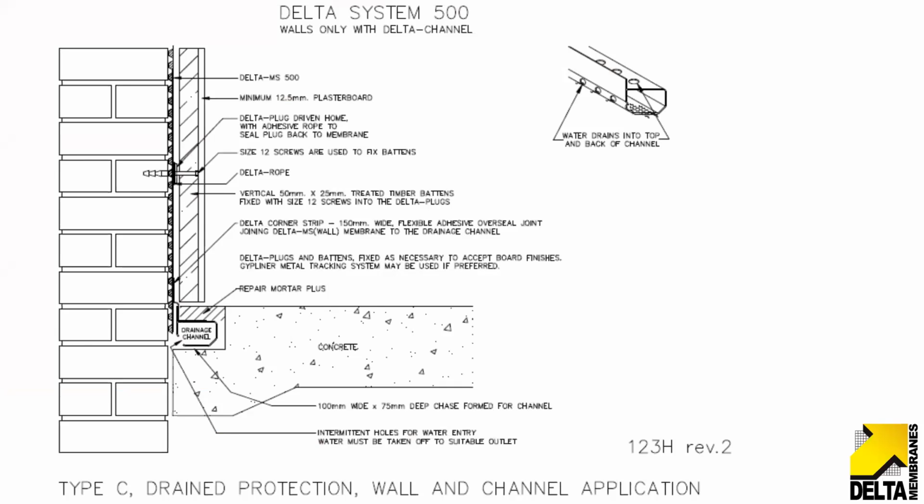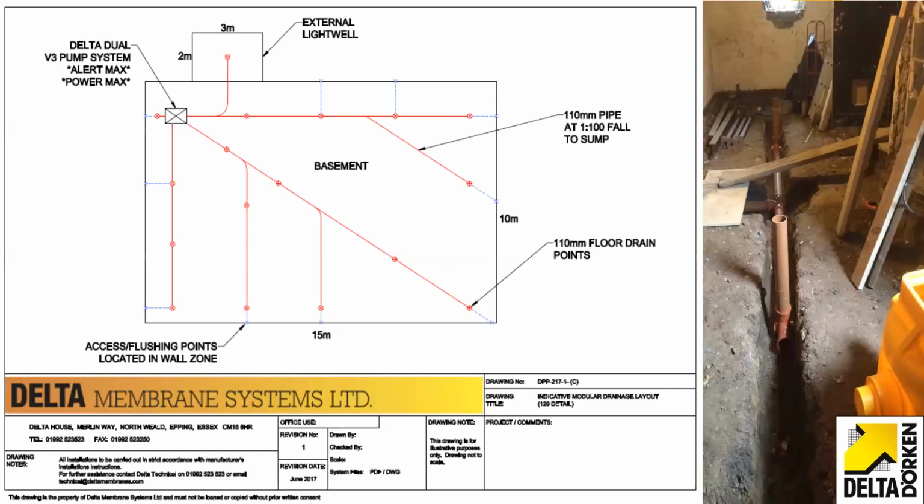We use the concrete structure and slab and/or a membrane under it to preserve the usefulness of the slab for driving forklift trucks over it and things like that. And we can do things like resins, a resin floor coating on top of the slab. So we deal with pressure at the edges where 99% of water comes in, and the walls, but we maintain a usable slab for industrial purposes.